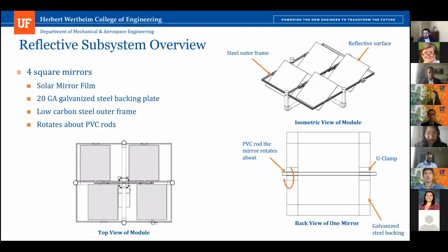Yeah, so the structure is basically 450 millimeter by 60 millimeter strips of galvanized steel, and those are overlaid in that square pattern that you can see along the outer edge. And since if you overlay strips, think of it kind of like Lincoln logs, you're going to have a gap, to flush out that gap there's another strip that sits inside of there.